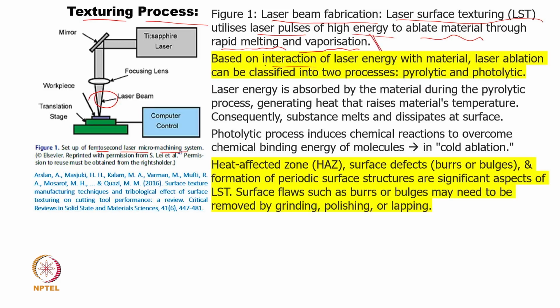However, based on the interaction of the laser energy with the material, the laser ablation process can be divided into two processes. One is called pyrolytic and the other photoelectric. In pyrolytic, rapid melting and vaporization happens, and that is what happens immediately.